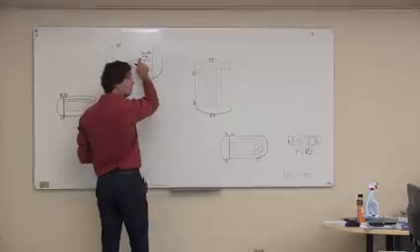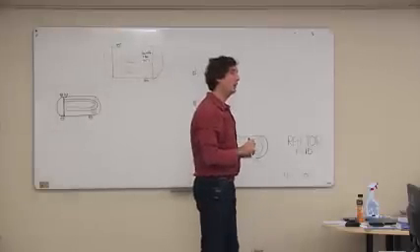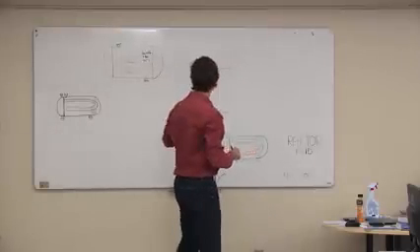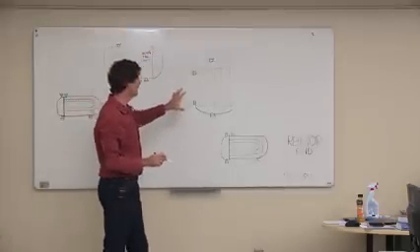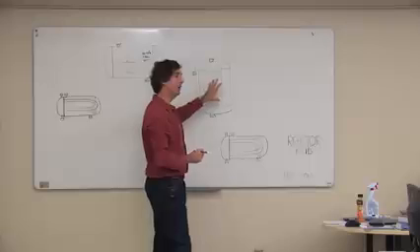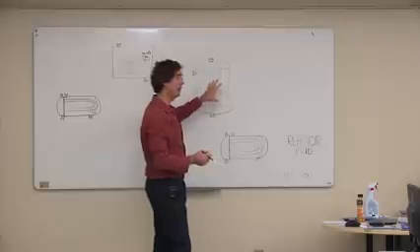Where did the 7 bar come from? That's the boiler feed water. Right. So we've got boiler feed water at 7 bar coming into the sheet, but we need to use it at 200 degrees Celsius. So that's going to be more like 10 or 12 bar or something like that. I don't know whether you guys have got the numbers handy or not.